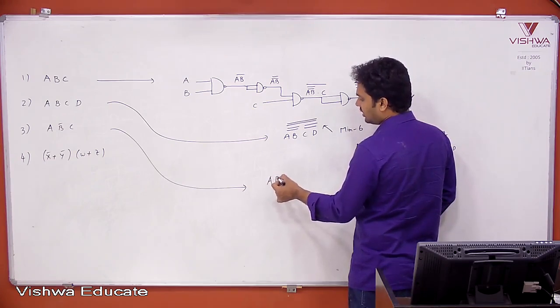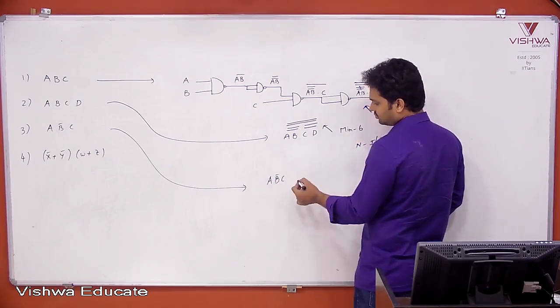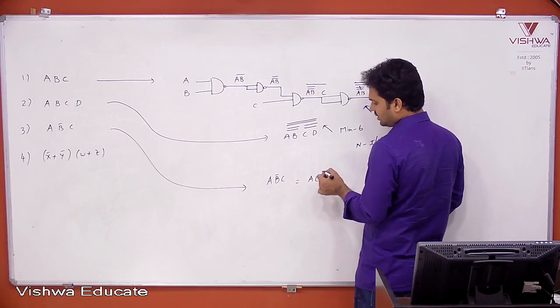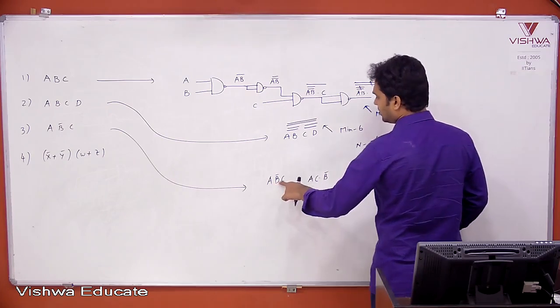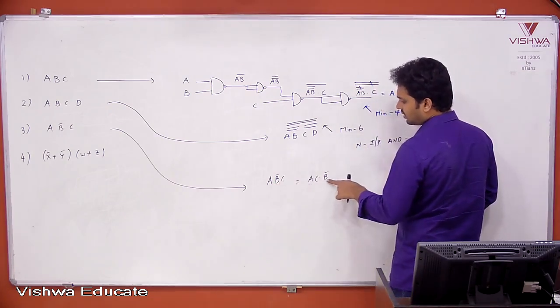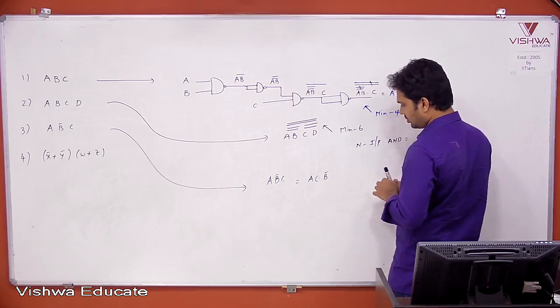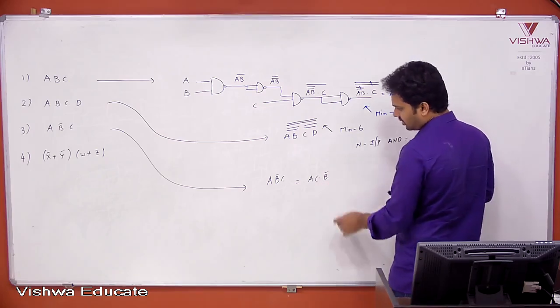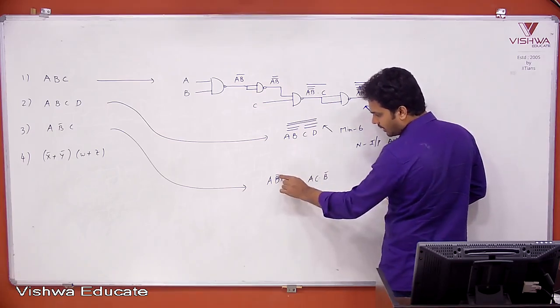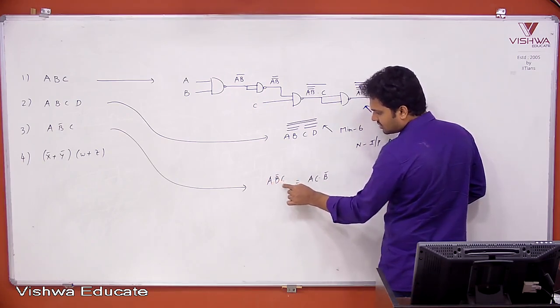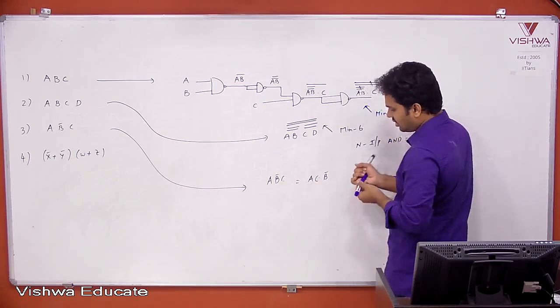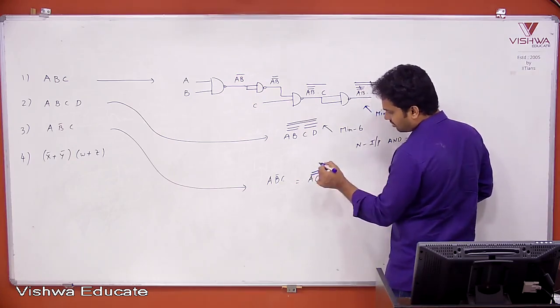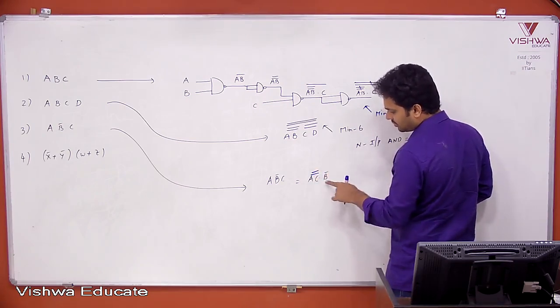Now, A, B bar, C. You can write it as AC into B bar. You keep C here, AC into B bar. Now you understand it is of product form only. Why I keep B outside: if the bar is in between A and C, it will make it complex. So make AC one side, B bar one side. Now take bars. Here double bar, that is AC bar whole bar is AC. B bar is one bar.